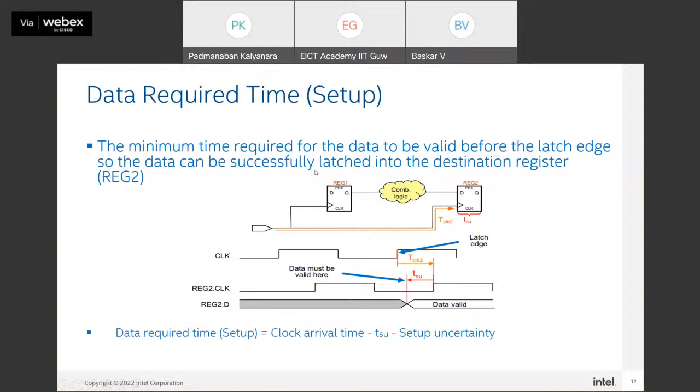Right, when we are applying the same clock, but then there is always a clock delay, right? There is a wire delay, right? So for clock 1 there would be a minimal skew because the same clock is reaching two registers, but then there is a difference in the net delay, right? Because the first flip-flop will get the clock here, there is a net delay which you can see, whereas the second flip-flop will get the clock later. There is a chance that the first flip-flop will also get the clock later. There is also a negative skew. We don't need to worry about that concept at this junction, okay?